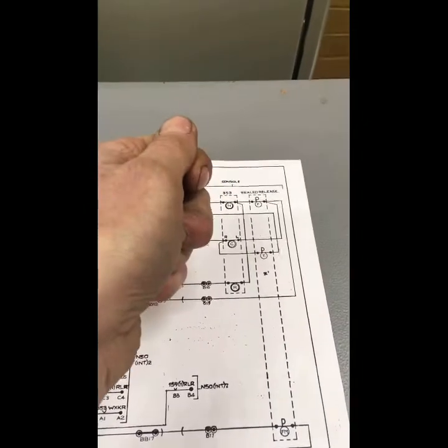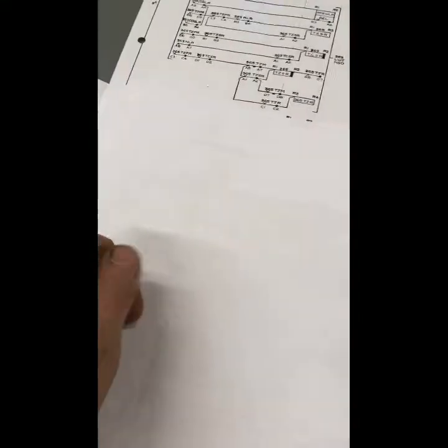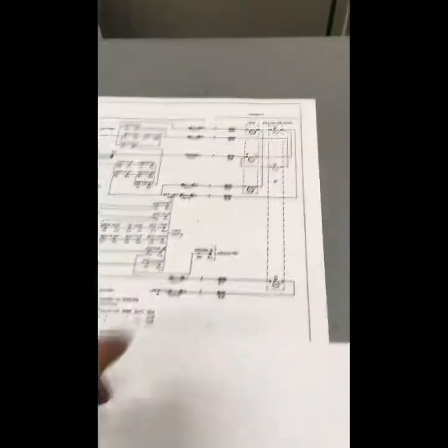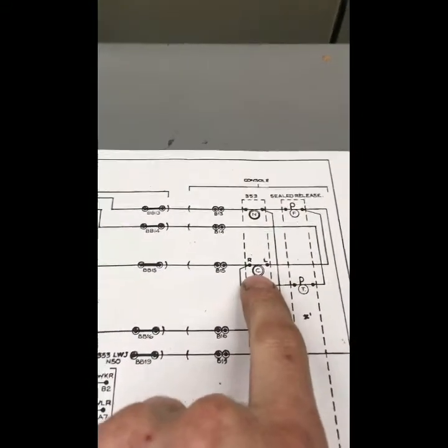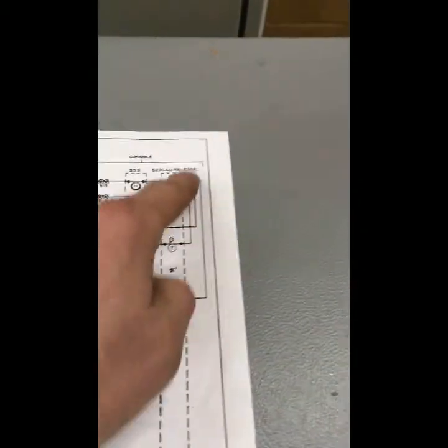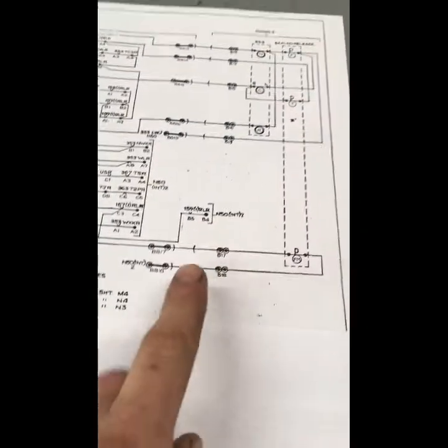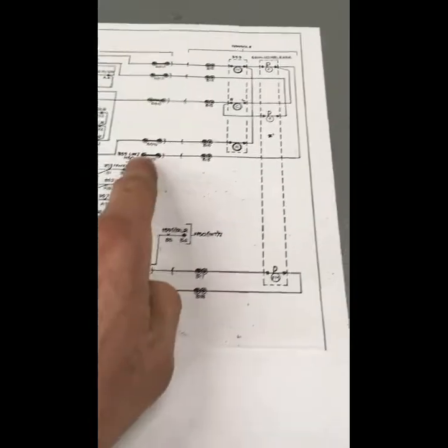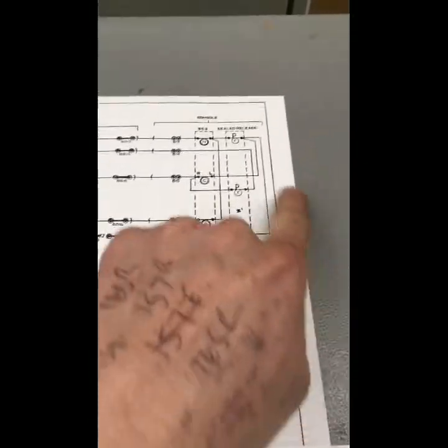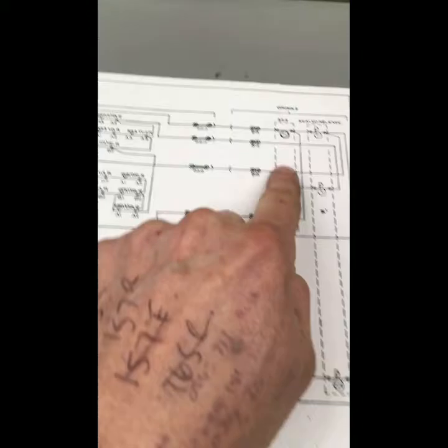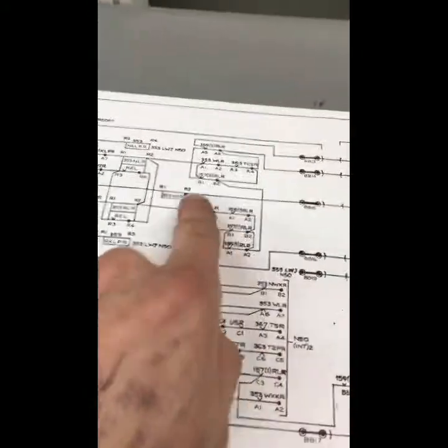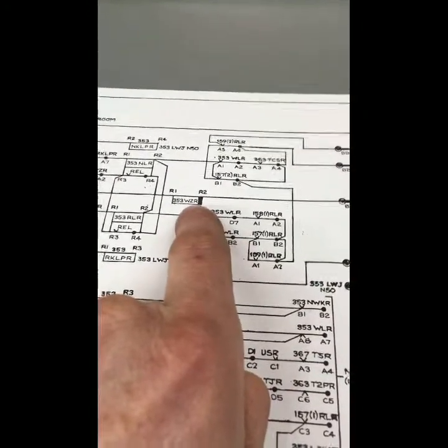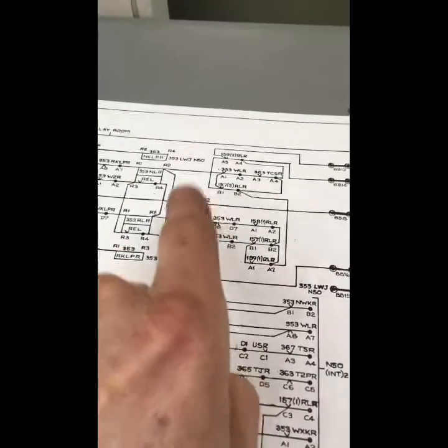Normally they should sit in the C, the centre position, and when he calls a route he will simply operate his signals button to button, or he will have route switches as he does here, you'll see that in the video, but normally it sits in the centre position. And what that does, that allows a 50 volt feed, which is all the way down here, in this case, this 50 volt feed to flow through to the centre. In flowing through to the centre, it goes through to the WZR. So that's telling the interlocking that I am free to be called.